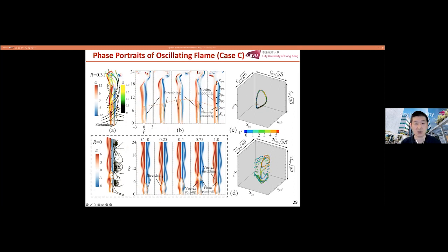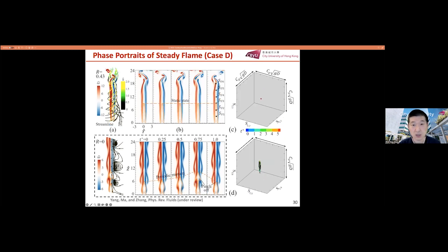If the flame is oscillating, the vortex shedding occurs downstream of the flame. So there is no chance for the vortex to nag the flame and make it pinch off. That's why we can only see the periodic motion downstream, which only slightly affects the flame, making the flame oscillate instead of flicker. Upstream, you can see there is no clear periodic motion. If we further increase the rotational intensity, you can see that the vortex shedding occurs much further downstream, and the upstream flame maintains a steady state.